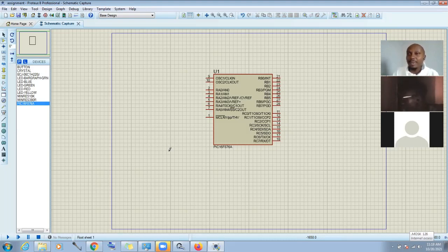We already established that this microcontroller has 2 VSS. I'm not sure what pins they are on here, but I think they should be on pins 8 and 19 or 8 and 20. That is on the physical layout of the board. The master clear reset is on pin 1. I'm not sure where the VDD should be, maybe pin 20. The VSS should be on pins 8 and 19. Okay. But here we don't need any of that.